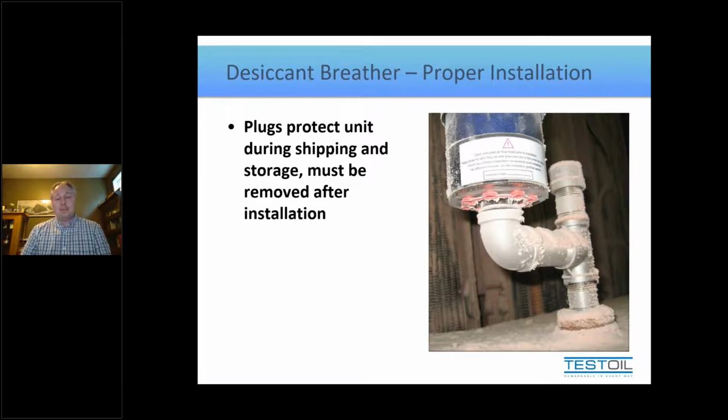So I was giving it the benefit of the doubt, because those of us who've been in industry a long time know that when these breathers first hit the market, one of the instructions was relating to the flow rate through the breather, that we would remove only a certain number of plugs. And the way you do the calculation, which I didn't reference at that point when you saw it on the slide earlier, is you take the gallons per minute flow rate that you have for oil, divide by 7.5, and that'll give you cubic feet per minute of air exchange.